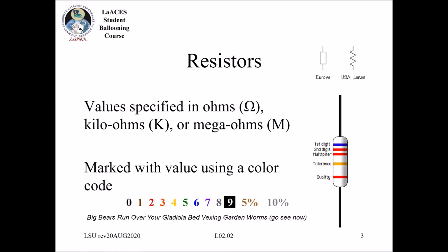So if you pick one up and you can't quite remember what it is, you could always get your meter out and measure the resistance, and then you'll get the value, and then you can confirm what it is. But you have to remember those tolerances in there.